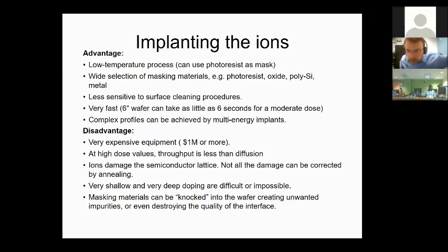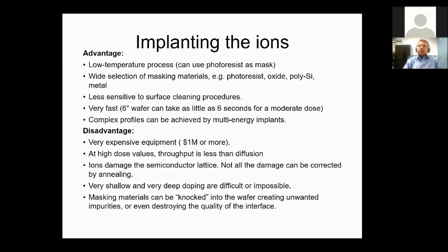That increasing the temperature, you should always keep in mind that there will be thermal expansion going on all the time between your layers. So there should be more and more stress build up. If you have like several cascaded layers, temperature increment can be critical. Also keep in mind that you might have polymers in your case, like you will see next week, like photoresist. They will be very susceptible to temperature deviations, and they can't really survive after 200 Celsius or so. So all those are going to be critical.